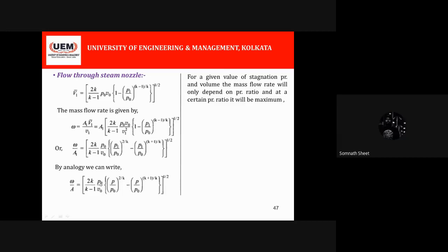Sir, because we assume that the velocity is almost negligible at inlet. Okay, velocity is negligible only at inlet. Yes, you are a bit correct, because we have told this several times. We are neglecting the inlet velocity, but I told that in respect of the outlet velocity being very high, so we are considering that the inlet velocity is negligible. But if there is some value of inlet velocity.